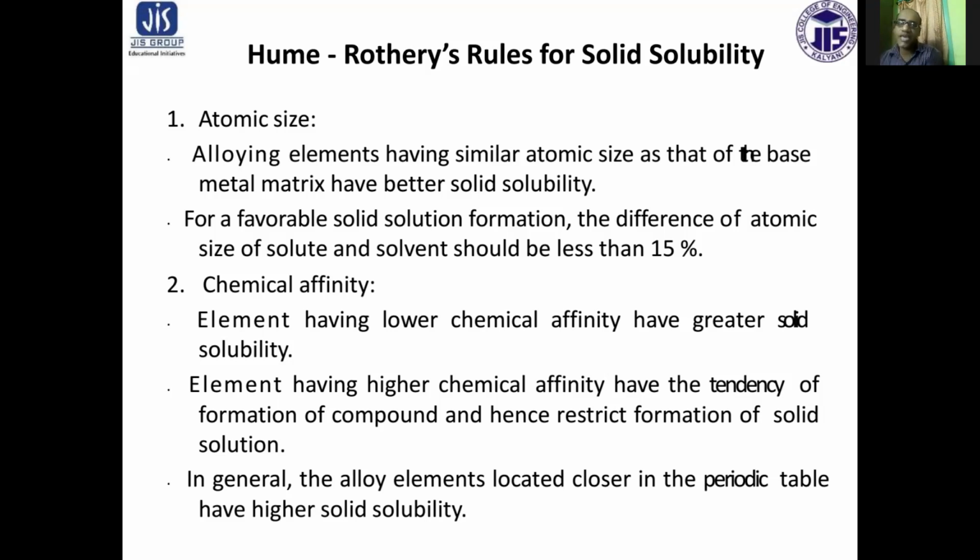Next is chemical affinity. Elements having lower chemical affinity have greater solid solubility. Elements having higher chemical affinity have the tendency to form compounds, and hence it restricts the formation of solid solution. In general, alloy elements located closer in the periodic table have higher solid solubility.